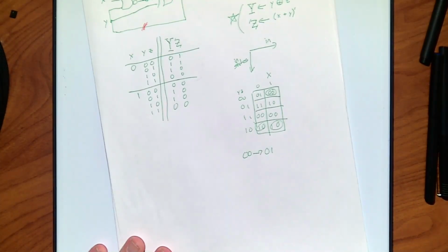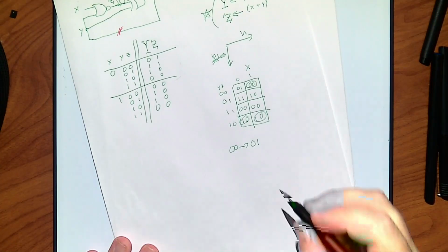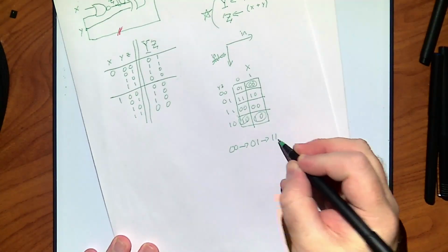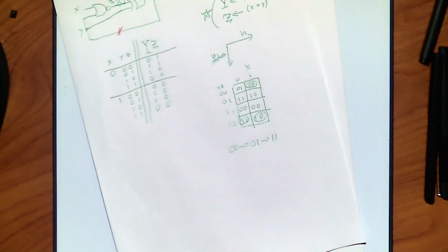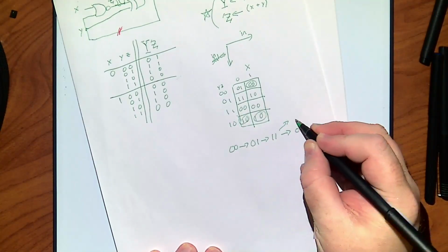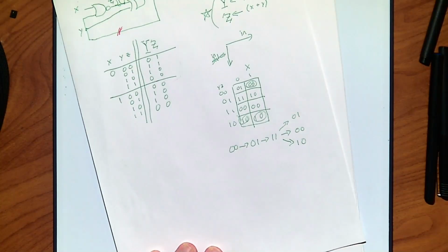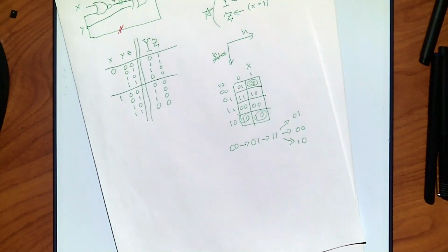Well, 0, 1, that's not. This is that warm-up lap. Everybody has to start at the same speed. And 0, 1 goes to 1, 1. Okay, we're jogging along. The second you get 1, 1, that says go to 0, 0. This is when the flag goes, and it's everybody for themselves. It could do what it was supposed to do, but it's possible that one bit flips faster than the other anytime you do those doubles.